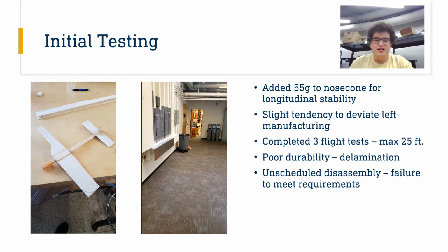Sadly, we discovered this vehicle suffered from poor durability due to delamination issues with the balsa wood in the wings, and we suffered an unscheduled disassembly on the 3rd flight test, which meant that this design would fail to meet requirements.